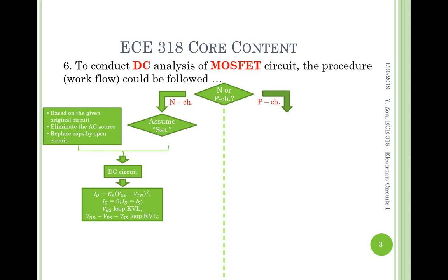The second one is from the VDD top supply to the bottom VSS supply, if any, going through the VDS voltage. So this is the KVL loop, second one. These should be sufficient. And before going ahead to do the calculation, you want to check one thing, to see if the number of equations is equal to the number of unknowns.